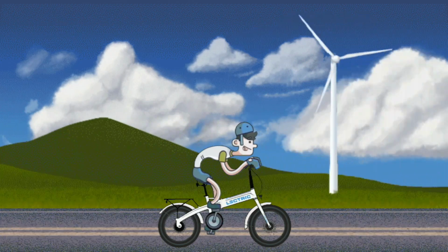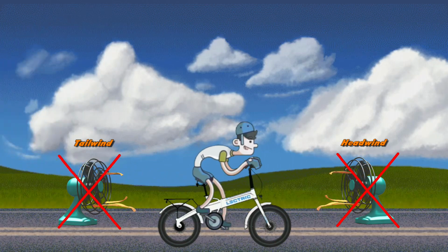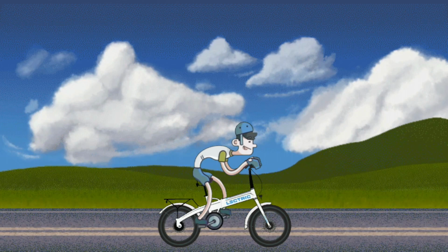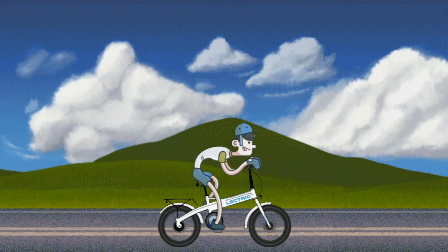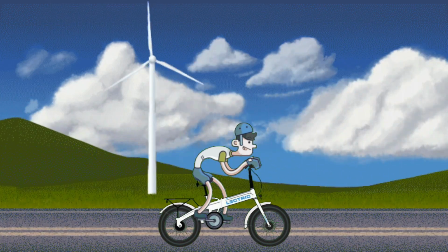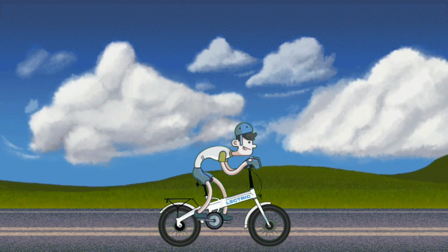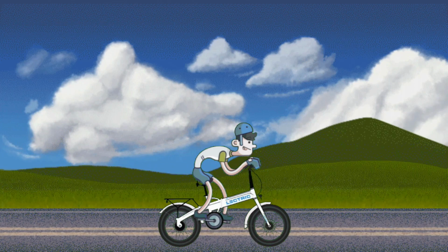While there is no wind blowing, take it out of any power assist mode. Place the e-bike in a comfortable gear, then pedal. Make a note of the speed that you feel comfortable pedaling at. Once that is complete, put the e-bike in any PAS mode, and use the throttle only, do not pedal. Make sure that the controller's LCD monitor is set to the current display. Turn the throttle until the speed matches the speed that you were previously pedaling, with no power assist.